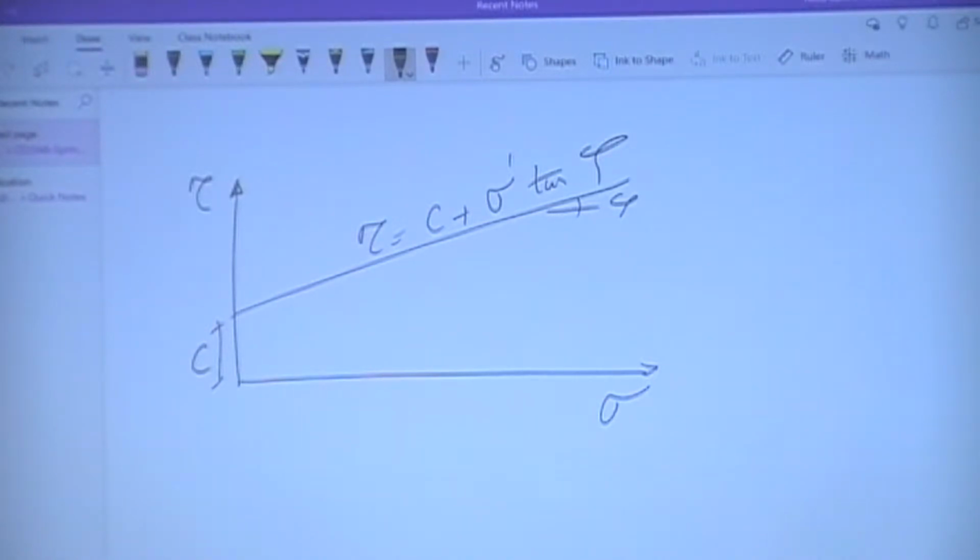By the way, if you look at that equation there, the higher the C value, the higher the sigma value, the higher the phi value, the higher the strength of the material, right? The strength of the material is on the left-hand side of that equation. And it has a direct relationship with the C value, phi value, and also the stresses that the material is experiencing. All right, so in very simple terms, we subdivided the strength of the material into two components. One component has to do with the cohesion, the other component has to do with the friction, right?